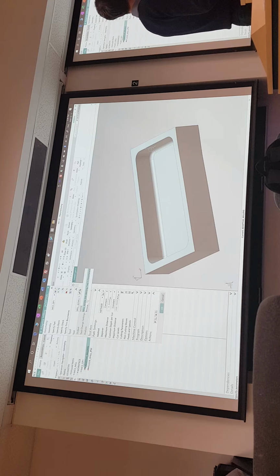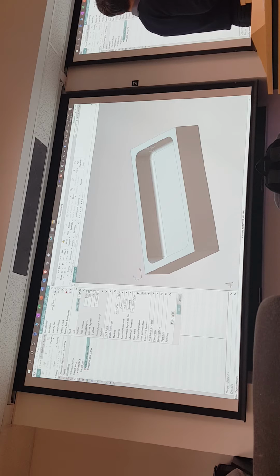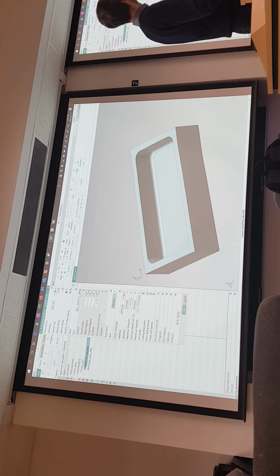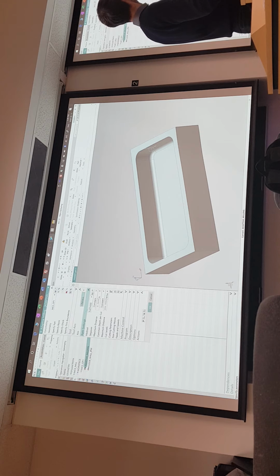We picked our tool. In this case, I said maybe a 5/8 end mill that I defined myself. When you're actually posting out a part, you have to pick the right tool number and register. And then I made the tool axis in line with the Z plus Z axis of my coordinate system. So I've done that, and now I go into my method. It's adaptive milling.